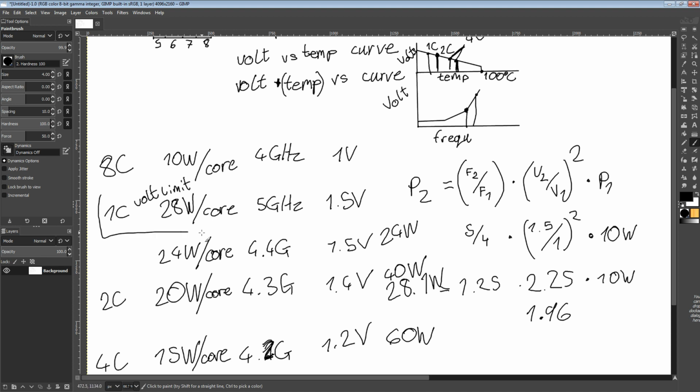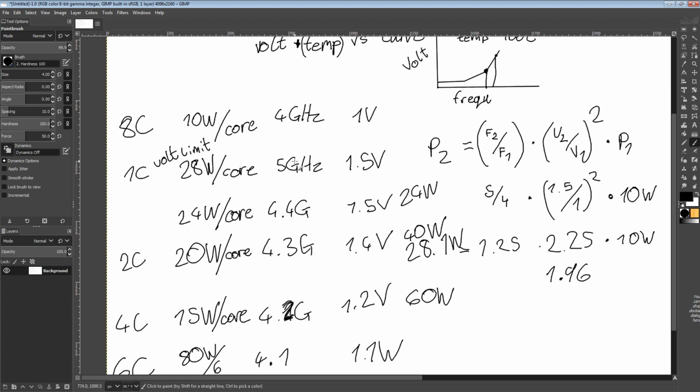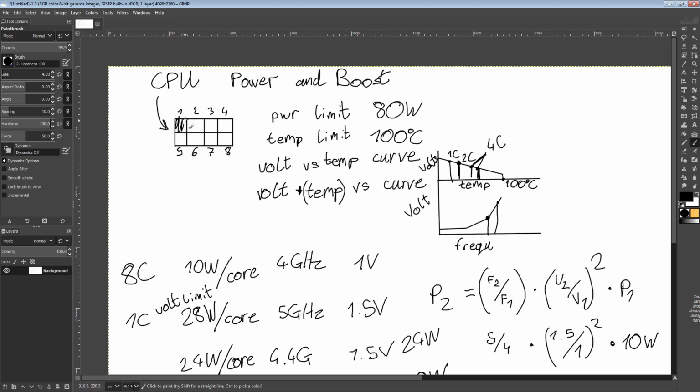But especially single core, very light workloads, they're just going to go absolutely nuts because the boost algorithm goes like, hey, the CPU has instructions to execute, and the goal of the CPU is to complete all instructions as quickly as possible. And so it's just going to max out the boost algorithm because it's like, well, if we finish them as quickly as possible, that's great, right? We're keeping the user happy. The side effect of that is that you're going to have really high temperatures.